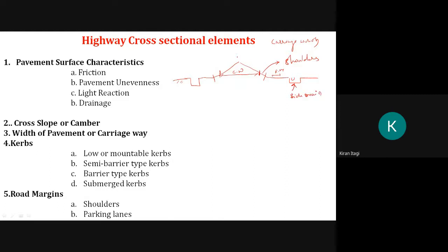Whenever there is a rainfall or any water spillage, it should go and be collected in the side drains. Suppose you provide the road completely flat, or if there is any sagging of the road in rainy season, you have already experienced this. The water will be collected here, which also leads to the damage of the road.